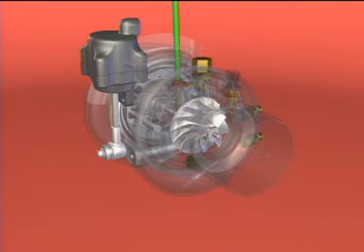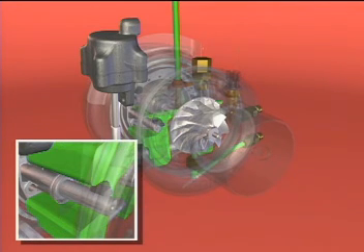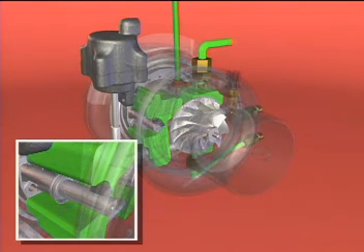On engines utilizing a VG turbo, coolant from the lower water manifold flows through external plumbing to the variable geometry turbocharger housing. The turbocharger housing is water-cooled to prevent overheating of the seals on the nozzle ring linkage. Coolant from the turbo is returned to the upper water manifold in the block. The pressure difference between the lower and upper water manifolds ensures a continuous flow of coolant to the turbo.